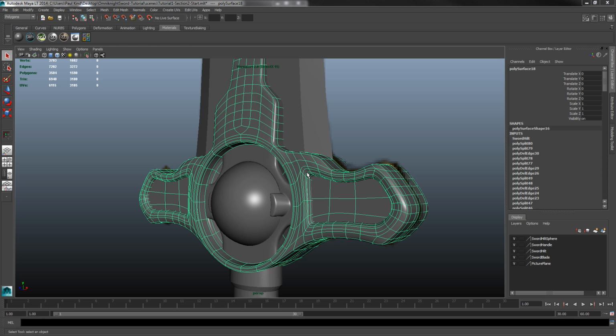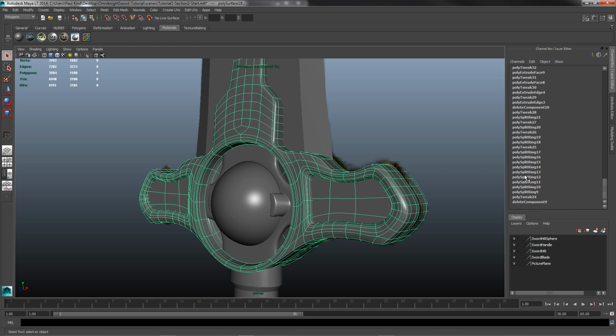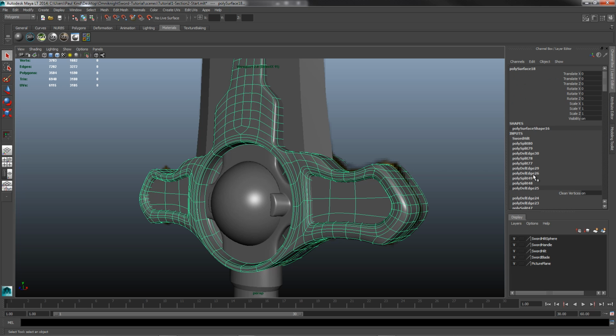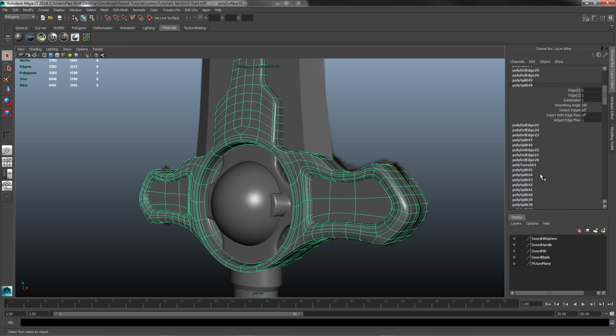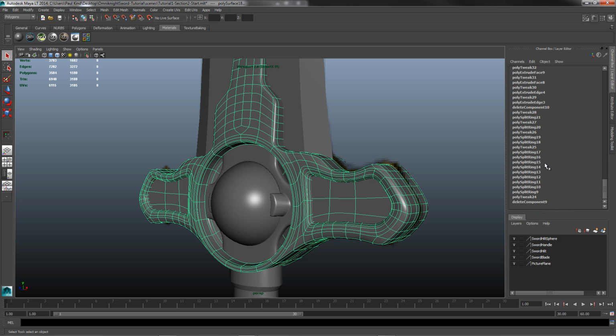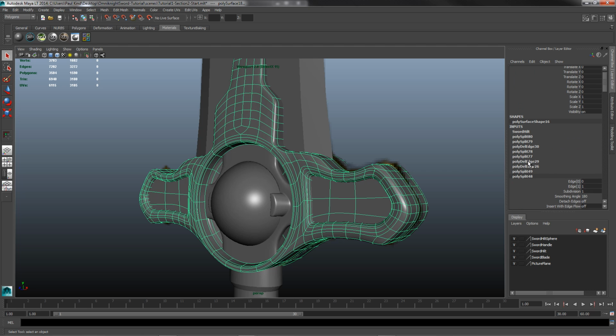Because the first thing we're going to do now is delete our history, okay? So basically, everything you do in Maya LT is going to start adding. So this is the first thing we did, and then this is the second thing we did, et cetera, et cetera. And see this big long list and how absolutely nightmarish it's become? Those were all the little changes that we've made throughout the process. I don't want to get into how to utilize that right now, because it's just okay. It's not the best history tool. So don't worry about it too much, but just know that there is this list of things that is happening to your object, and of course, the more there are, the more complicated it becomes. I mean, look at this list; it's ridiculous, right? So we want to get rid of that list and make it so that this is our object now, and this is our raw mesh.